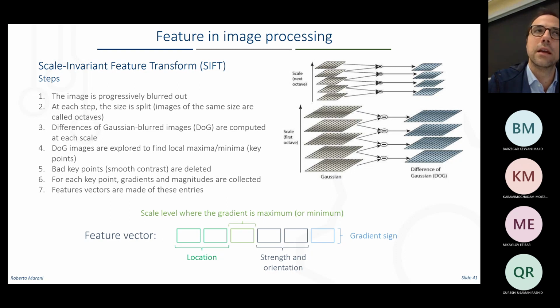feature extraction technique where you smartly create many representations of your image. How do you create your representations? You take your input image and then you apply some blurring. Blurring means that you're using a convolutional filter with a Gaussian kernel. For those of you who, like me, have a problem with your eyes, it is the same as taking your glasses off. So this is an image completely blurred, the result of a convolution with a Gaussian filter.